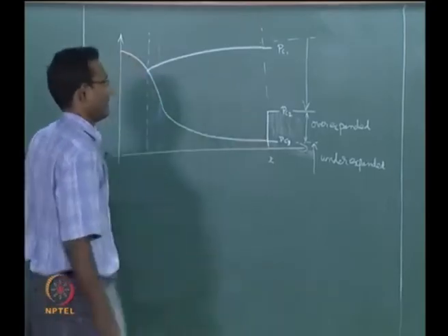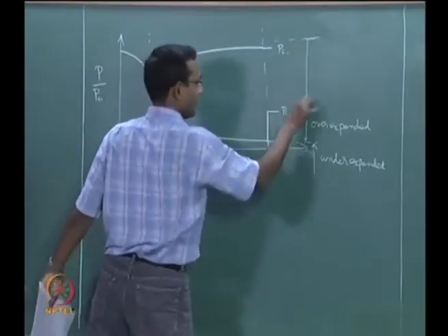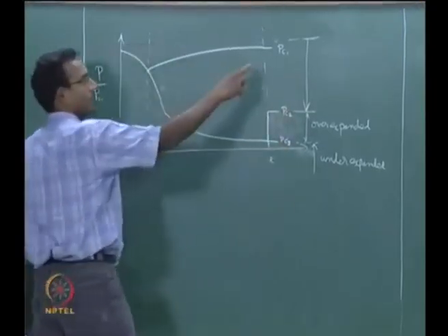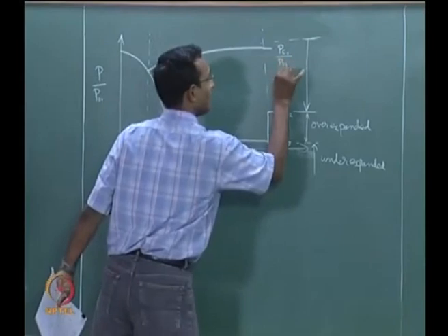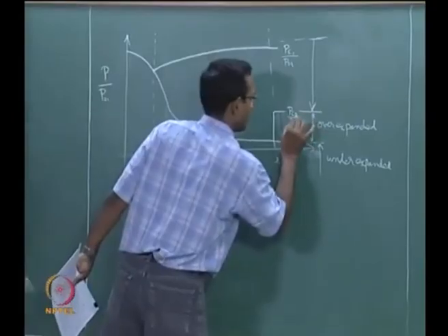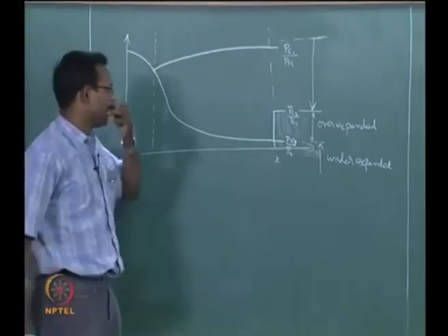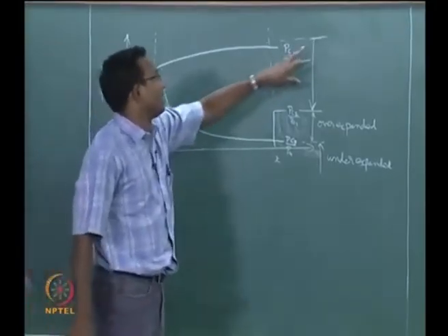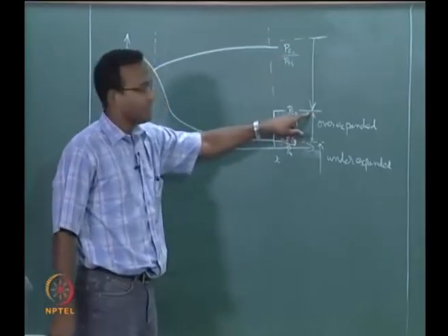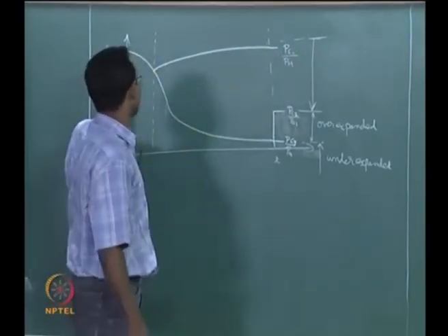So from Pb equal to P01 till Pb equal to P critical 2, everywhere this is what is happening. Oh, I am confusing here, it should be P critical 1 divided by P01 here, because I am plotting P by P01 as my axis. It should be non-dimensionalized everywhere. Anyways, so from Pb equal to P01 all the way to Pb equal to P critical 2, everywhere I have already solved this, and we know that up to P critical 1 there will be no shock inside, completely isentropic.